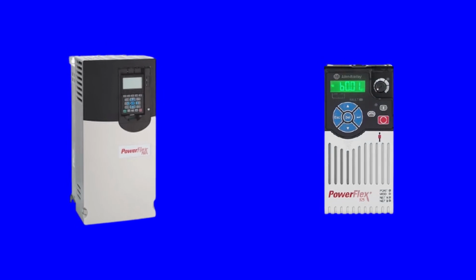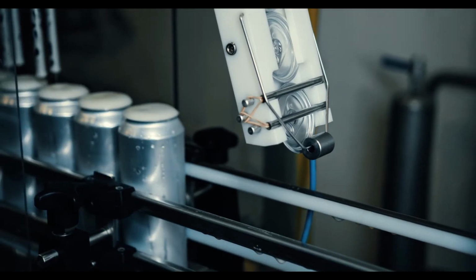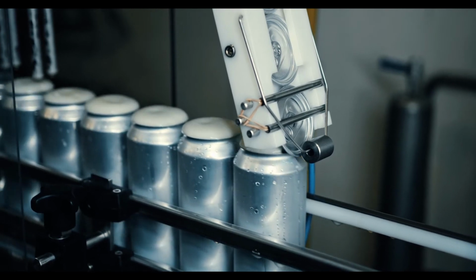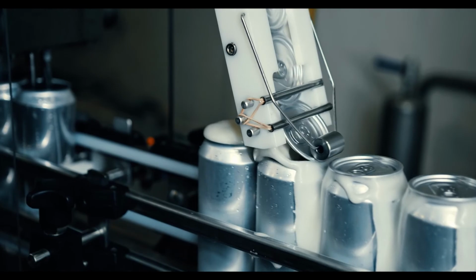If you happen to have a PowerFlex 750 or 520 series, you're in luck. They're both outfitted with a 7th IGBT, which acts like a built-in brake chopper or brake module. If, however, you're using a different sort of drive, you will likely have to purchase a brake module along with your brake resistor in order to have the complete system.